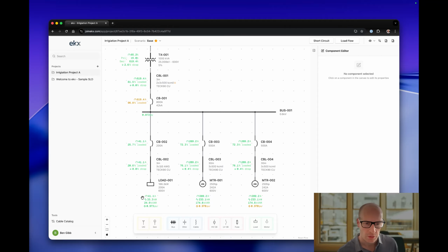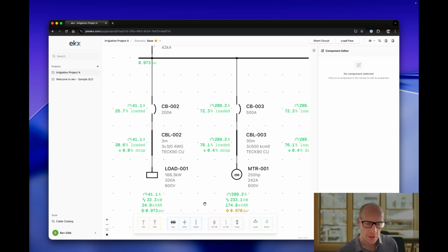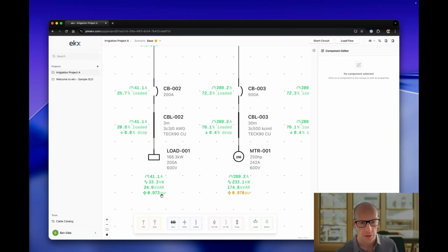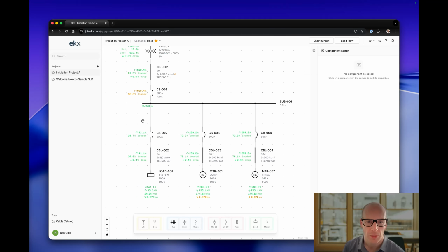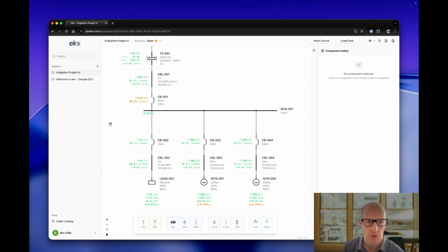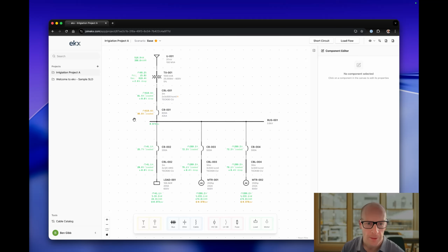The lighting panel only taking about 40 amps because we've derated it. Not derated it, but have a lower demand. This is not bad. I don't want to review this again, but something just to whip up. Gives you a good idea of what kind of distribution equipment you would need.